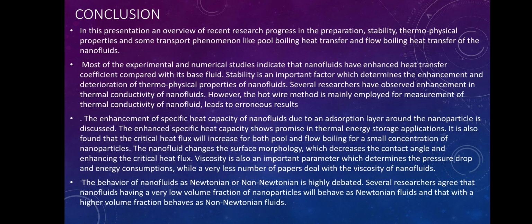It is also found that the critical heat flux will increase for both pool and flow boiling for a small concentration of nanoparticles. The nanofluid changes the surface morphology, which decreases the contact angle and enhances the critical heat flux. Viscosity is also an important parameter which determines the pressure drop and energy consumption.